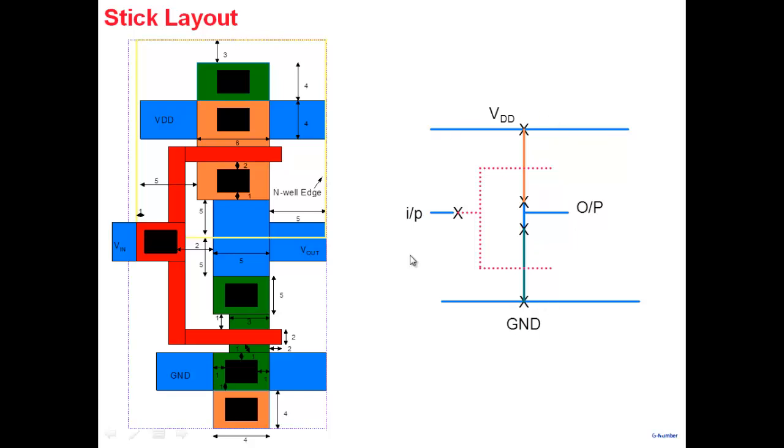So this does carry some information about the structure, because note that once I create something of this kind, how do you arrive at the full layout? You have to add the size information. And where do I get the size information? From all the rules that are there. Plus, I also have the size of my MOSFET: W by L of this particular MOSFET is known. So I have the size of the MOSFET and all the rules.